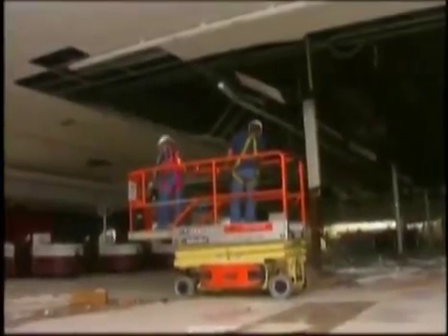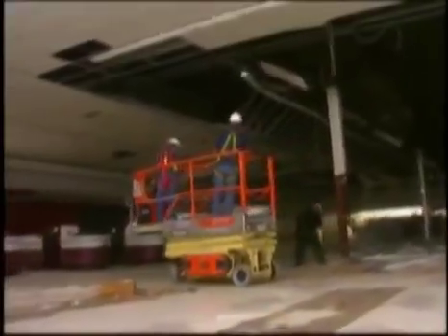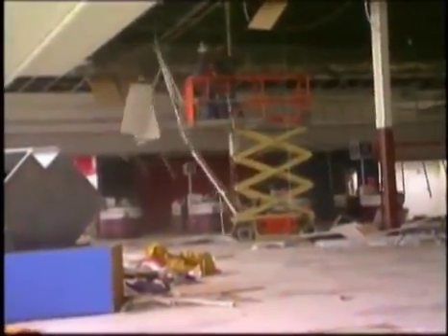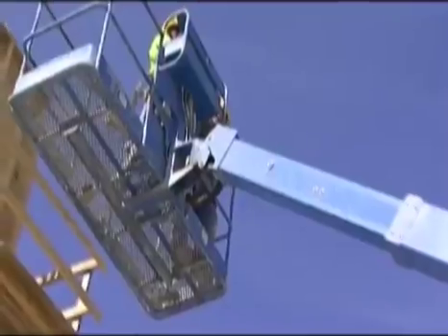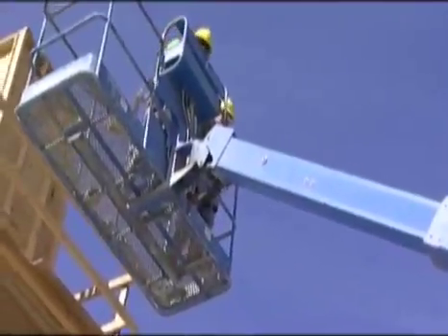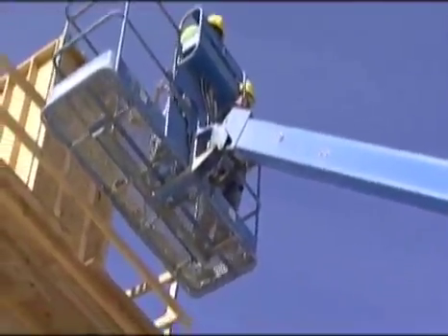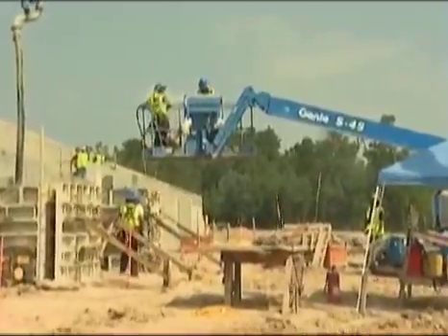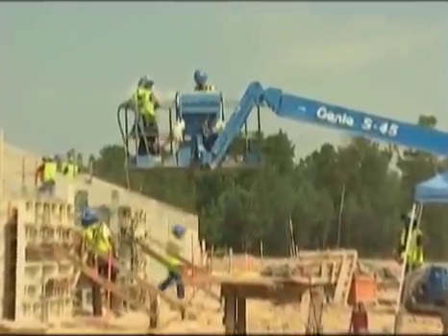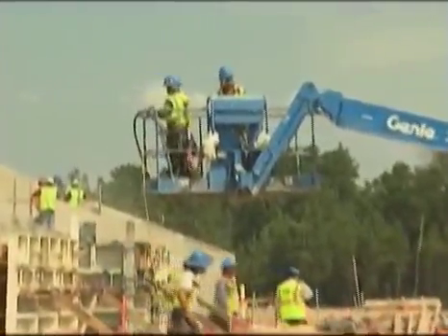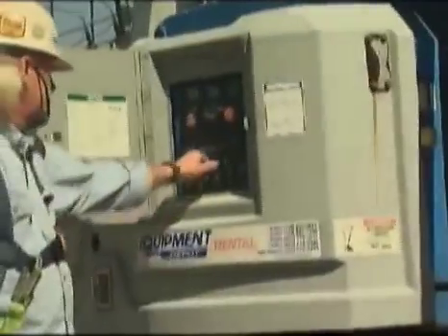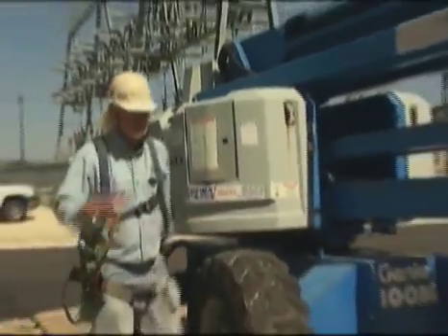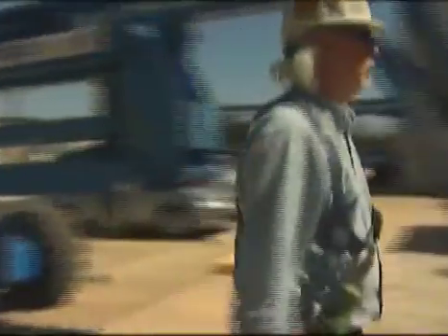Only authorized and trained persons should operate an aerial lift. Never tie off to an adjacent pole, structure, or piece of equipment while working from a lift. Personnel should always stand firmly on the floor of the lift. Never sit or climb on the basket or guardrails, or use planks, ladders, or other items to attain a higher work position. If additional height is needed, then the lift should be extended, or if necessary, a different lift used that is appropriate for the job. The lift operator should know the total load of the lift, including tools, supplies, and other employees.